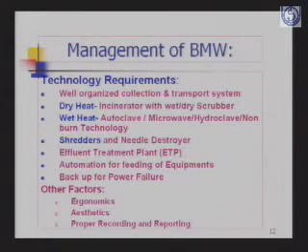What are the technology requirements? First is a well organized collection and transportation system. For dry heat we can use an incinerator with wet and dry scrubbers. For wet heat we use autoclave, microwave, hydroclave and any other non-burn technology. Shredders and needle destroyers, then an effluent treatment plant, automation of feeding equipment is a must, and backup for power failure because of a lot of power breakdowns. Other factors we should keep in mind: ergonomics, aesthetics, and proper recording and reporting.